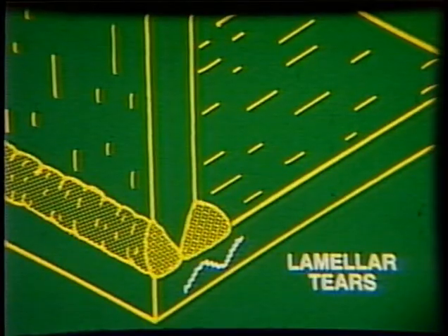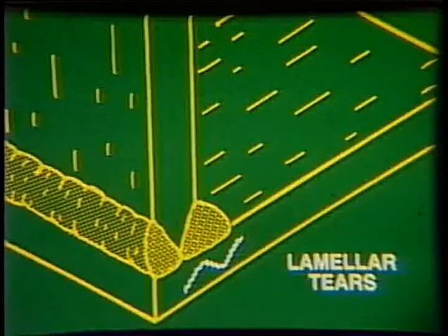Lamellar tears are discontinuities that occur during or after welding and usually appear as a stair-step defect caused by contraction forces during solidification. Lamellar tears may extend over long distances and are located deeper than heat-affected zone cracks, which differ in shape, cause, and location.